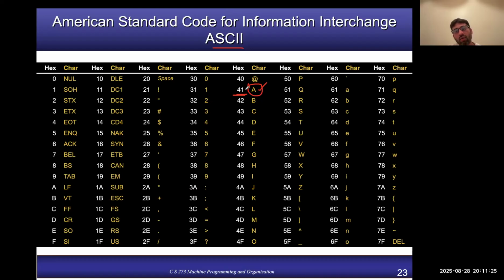So when we press A, the digital hardware will receive the binary of the hexadecimal value 41. Remember from the previous lecture how we convert: we replace each character in hexadecimal form with 4-bit binary. So 4 becomes 0 1 0 0 and 1 becomes 0 0 0 1.